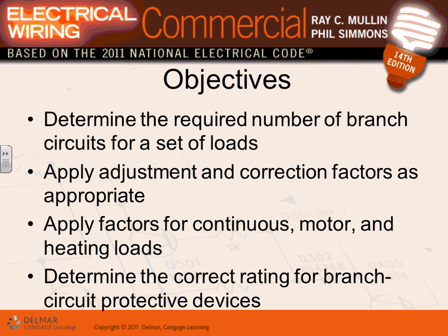You would be foolish not to group all your 20 amp circuits in a 3/4 inch conduit as you get them out of the panel into a junction box, and then you spread them right through your building. You don't want to run a half-an-inch EMT conduit out of this panel for every single branch circuit you have. You'll have tons of EMT conduits. So we get into grouping. Why grouping? Because it's economical to group multiple circuits into one conduit as you get them out of the panel into the ceiling, so you can spread them to feed the lights and the receptacles.